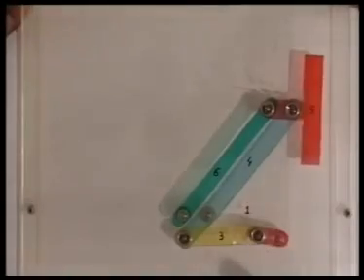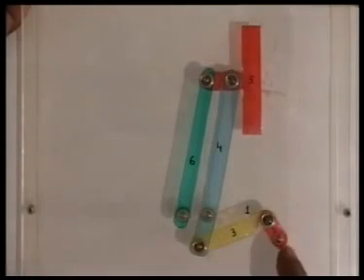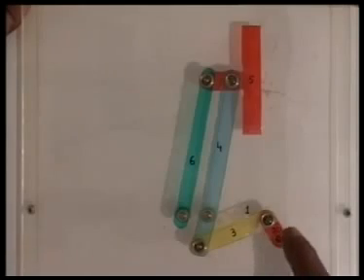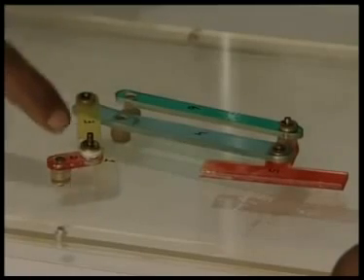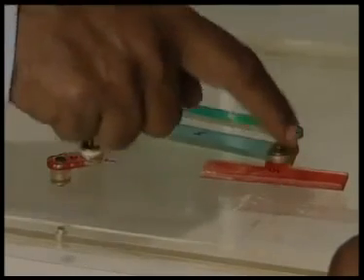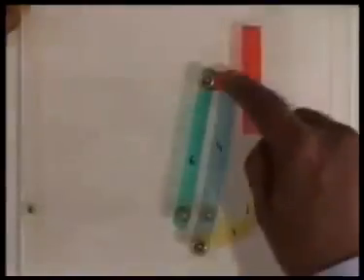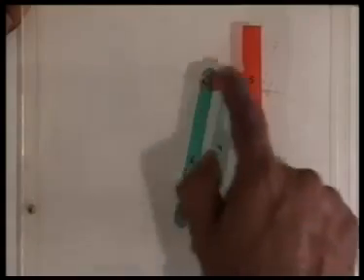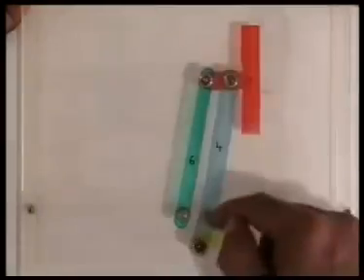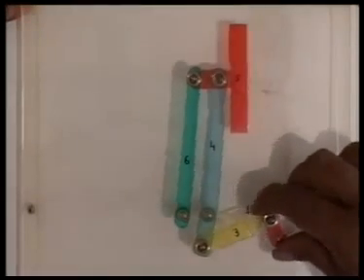We demonstrate the same wiper mechanism that we have just now studied. This is the same wiper mechanism consisting of a crank rocker consisting of link 2, link 3 and link 4. O2 and O4 are the two fixed hinges. And there is another parallelogram linkage starting from here, link 4, link 5 and link 6. This link length is the same as this link length and this link length is the same as this link length. So, it is a parallelogram, and we should note, because it is a parallelogram linkage, the coupler always remains parallel to itself; it never changes its orientation.